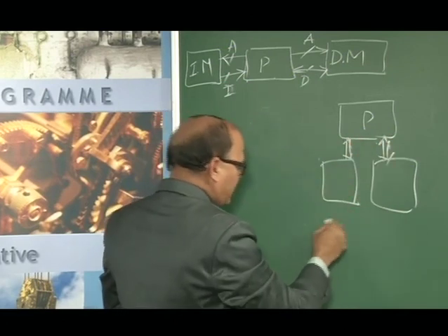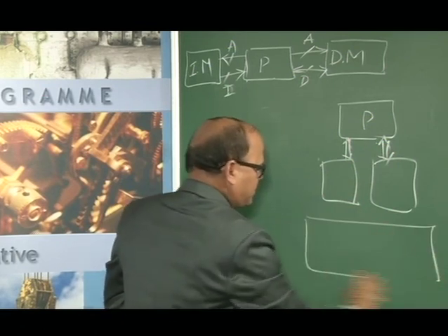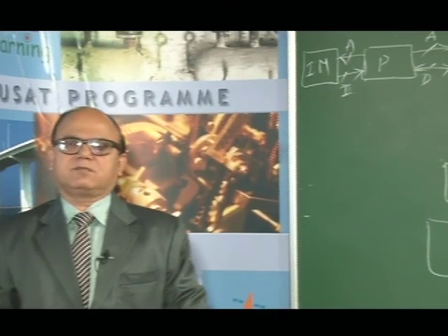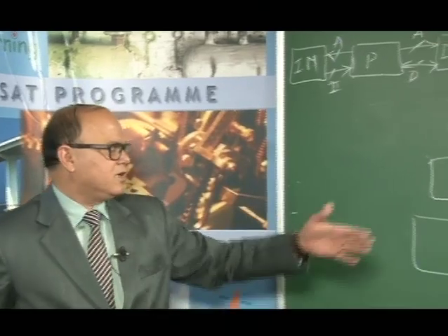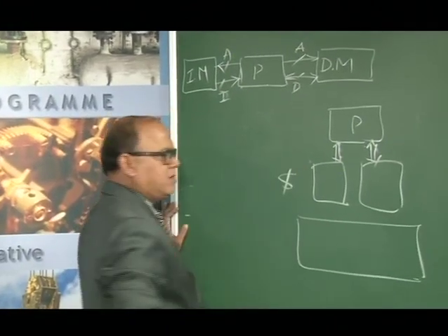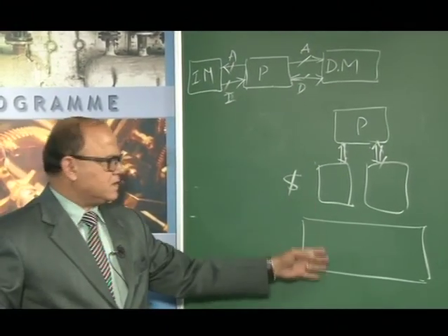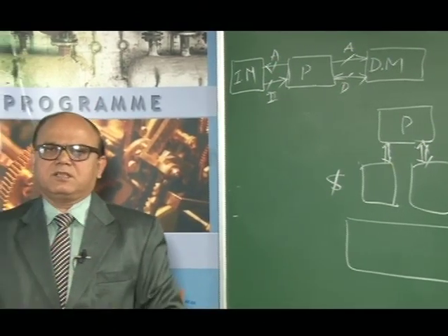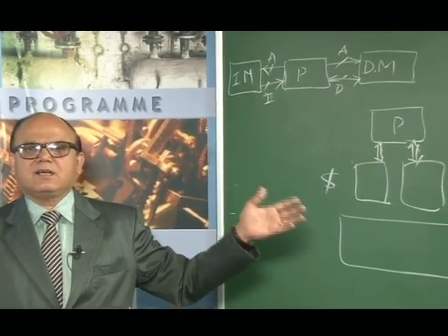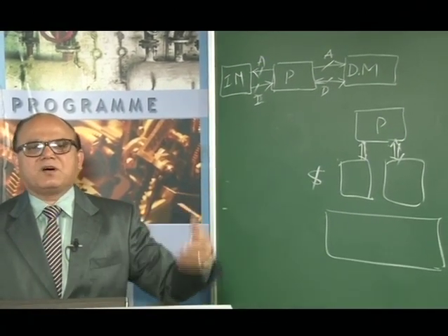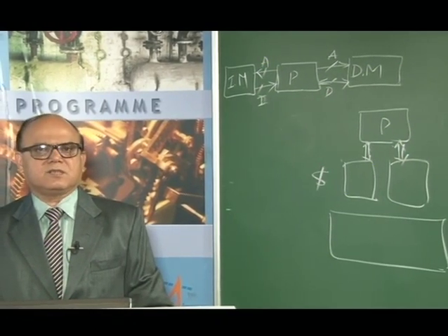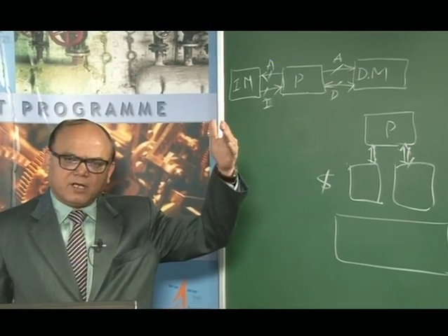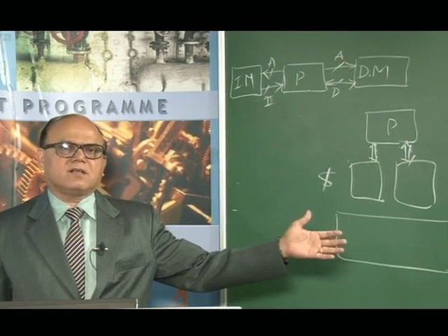So we can have it like this, or the subsequent level of the memory could be monolithic also. In other words, in the hierarchy of the memory, the cache is split vertically. Let me call this the on-chip cache. So this is the on-chip memory, but the memory is unified, and then the cache is split. So I'll say that it is a mix of von Neumann and Harvard, right? Because one level is split vertically, and the other level I have not split.